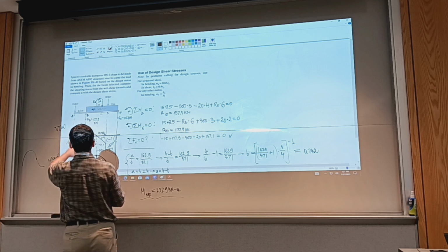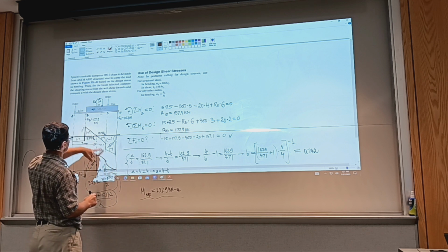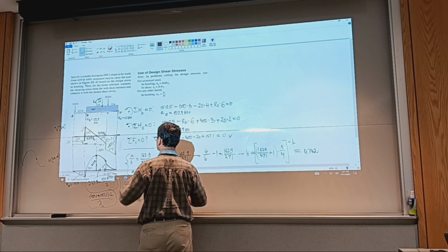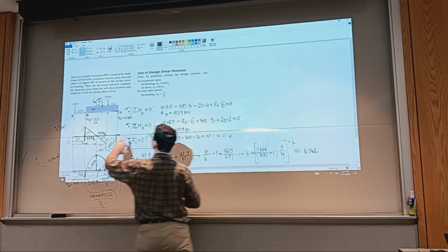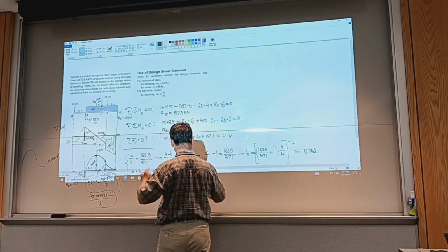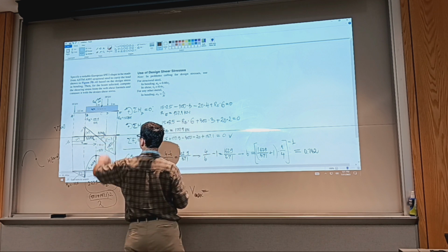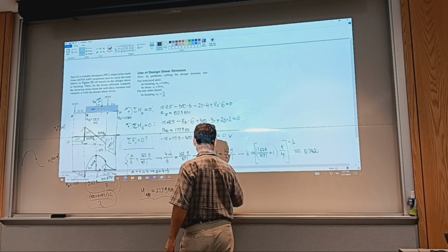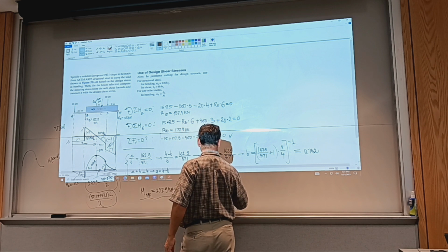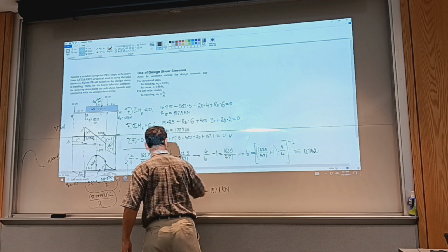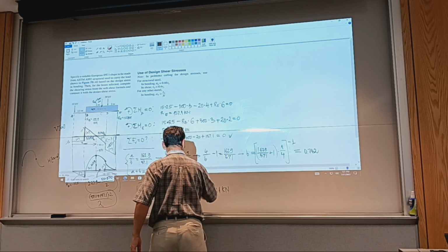And then I also need to, so it was a maximum bending moment, or rather shear, I apologize. So maximum shear happens at D. So V max, this is going to be 157.1 kilonewtons. So these are the two values that I'll be working with.